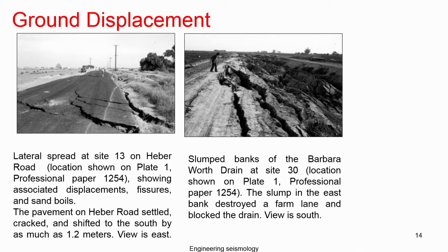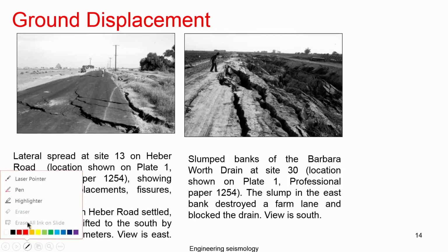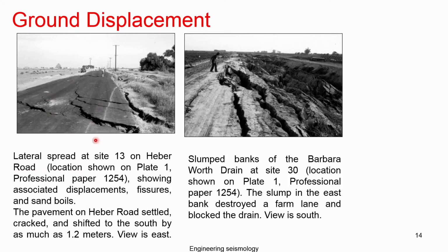So, when the individual particles, cohesionless soil, where you can see the particles by the plain eye. Okay. That soil we call a cohesionless soil. This soil does not have much attraction between the particles. So, in those kinds of places, when the vibration comes, this vibration basically tries to move the particles. The moving of particles basically results in the moving of the ground layers. You can see this is actually the ground layers' movement, which basically causes the permanent ground displacement.